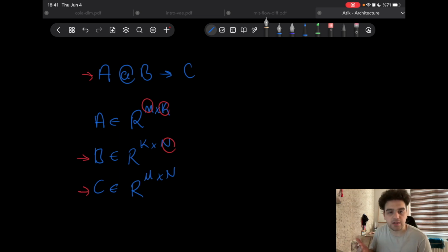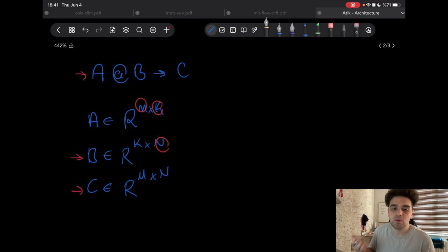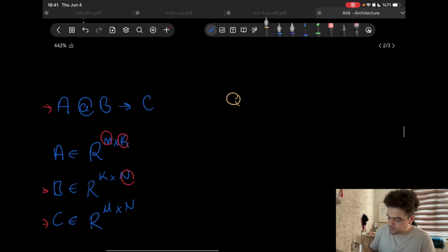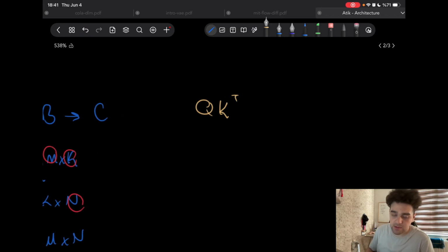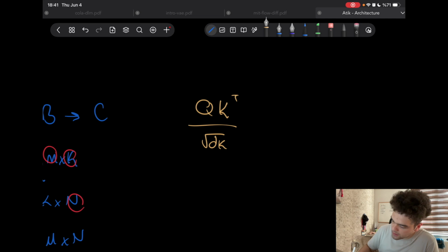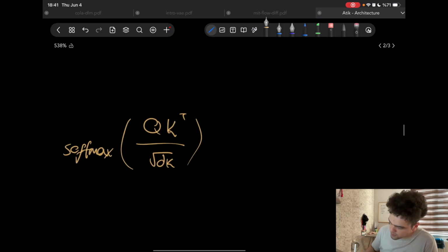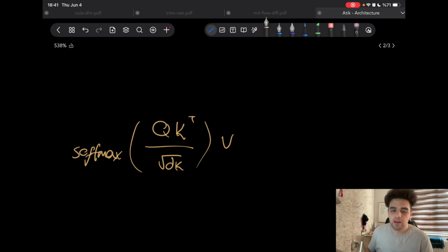Because our accelerator will do more than matrix multiplication, it will also calculate attention, we should also take the scenario of the attention mechanism into account, not just formulating the math model for matrix multiplication. So we need a Q matrix and a K matrix, which will be transposed. Then we will normalize this by the square root of dk, which is the dimension, and we will take the softmax along a specific dimension, for convenience the 0th dimension. Then eventually we will multiply by the value matrix.